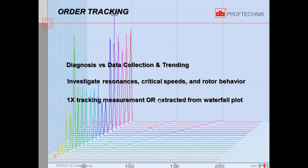The second method is tracking the full spectra as a function of RPM. In the background on this slide, we have amplitude along the y-axis, frequency along the x-axis, and it's not labeled, but that would be RPM along the z-axis going into the slide. So, one of two ways to implement order tracking.